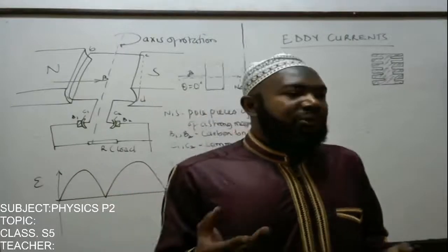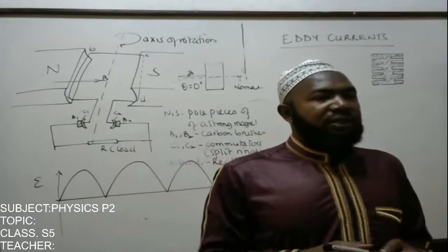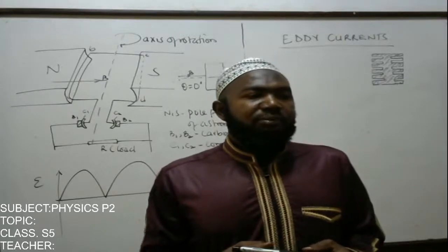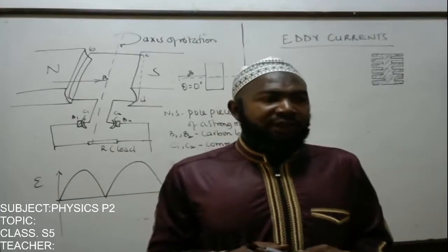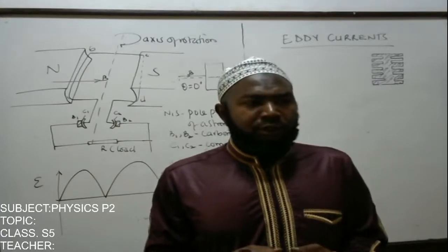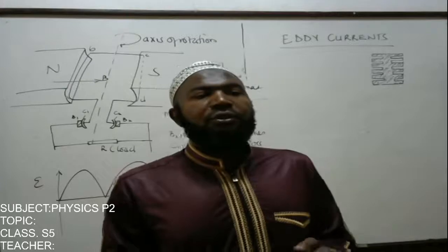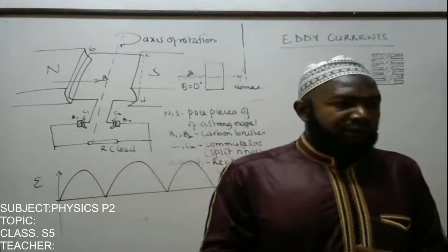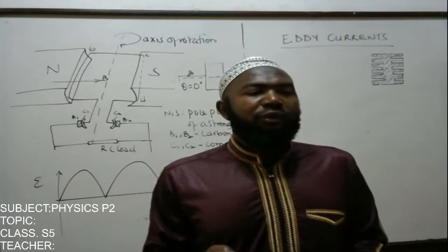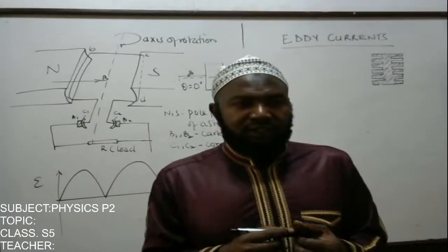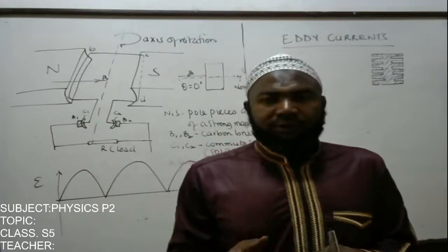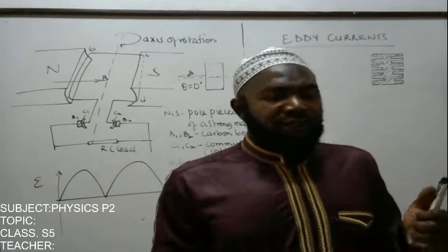Three is the speedometer, or generally speed meter. In a speed meter, there is a small magnet inside the speedometer that is producing a changing magnetic field. The eddy currents are set up in the drum onto which the pointer is attached, and the pointer indicates the speed upon attaining equilibrium. So that is the third application.